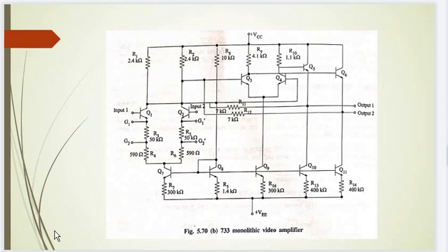This IC consists of two cascaded BJT differential amplifiers and a balanced emitter follower stage. By the use of an internal feedback loop, a wide bandwidth is achieved. The input is given to the transistors Q1 and Q2. The transistor Q7 provides the current sink biasing for the first differential stage. The negative feedback path is provided by the resistors R3 through R6.